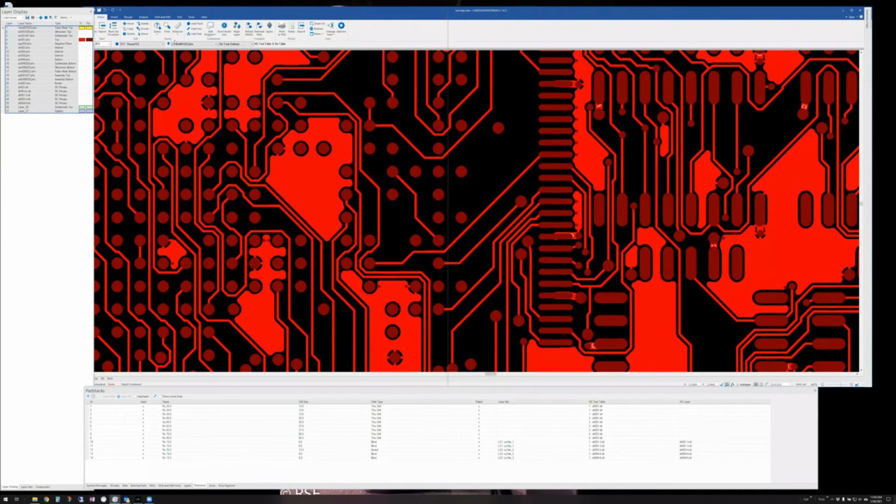Understanding the difference between decode, pad stack, flash, and how to add them or remove them or redefine them, and in which situation do we use them? Okay, well, pad stacks is more of a CAD term. When I extracted a netlist, it created pad stacks, which basically is all the pads that are in this design.